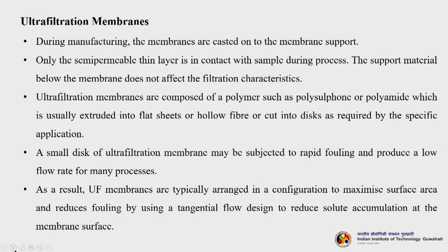So, carrying and transportation is a big problem. If there is a big plate type of membrane, okay, fixing it has to be done very carefully. Little pressure on that will actually damage the membrane, and the entire flat membrane can break. So, this is why most of the ceramic ultrafiltration membranes are actually tubular.